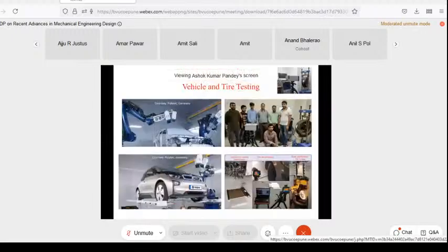Now, after this modeling, mostly we try to do the testing of the vehicles and even the tire testing. So, what are the tools which are available? Of course, the most conventional tool for testing is accelerometers, right? You put accelerometers all over, and then you do testing, isn't it? And then from there you do modal analysis and try to generate the mode shapes of all these vehicles. Then you know which component is having what frequency and what mode shape, and you try to reject some of the mode shapes, so that when the vehicle is on the move you don't get disturbance from those components, because they may start oscillating, right?